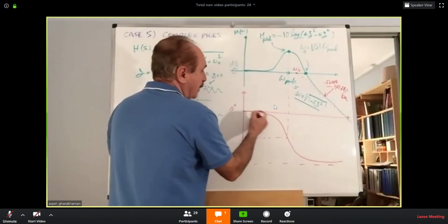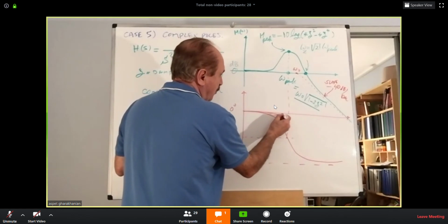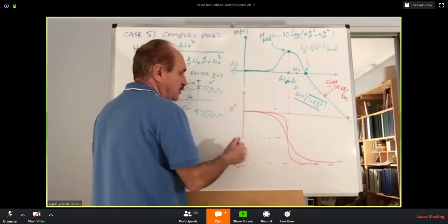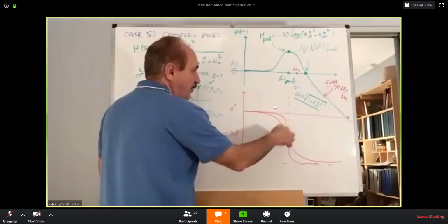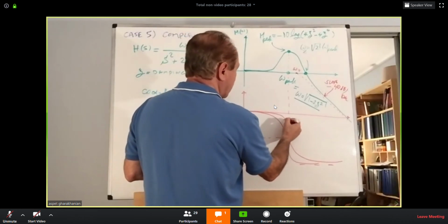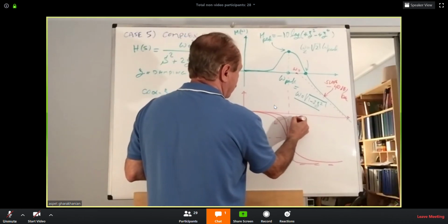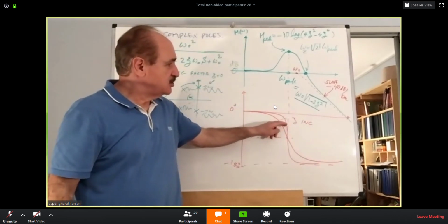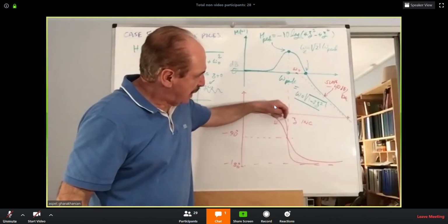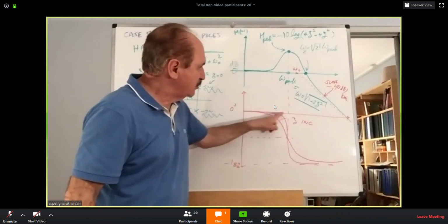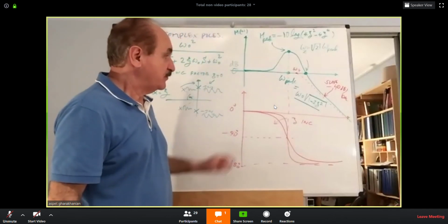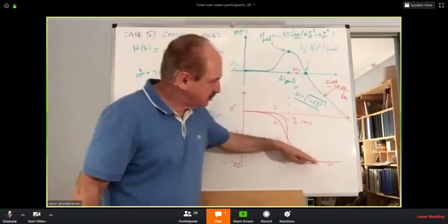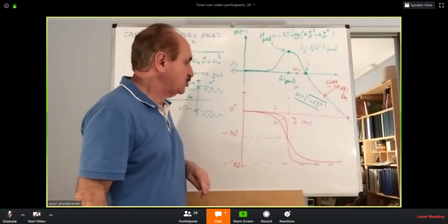And as zeta gets smaller, the decline at that point towards the 90 degrees will be even sharper. So here, zeta is increasing in this direction. If zeta is 0, it will be quite abrupt, almost like a step in the phase change. As it is increasing, the transition of the phase angle will be much, much smoother.